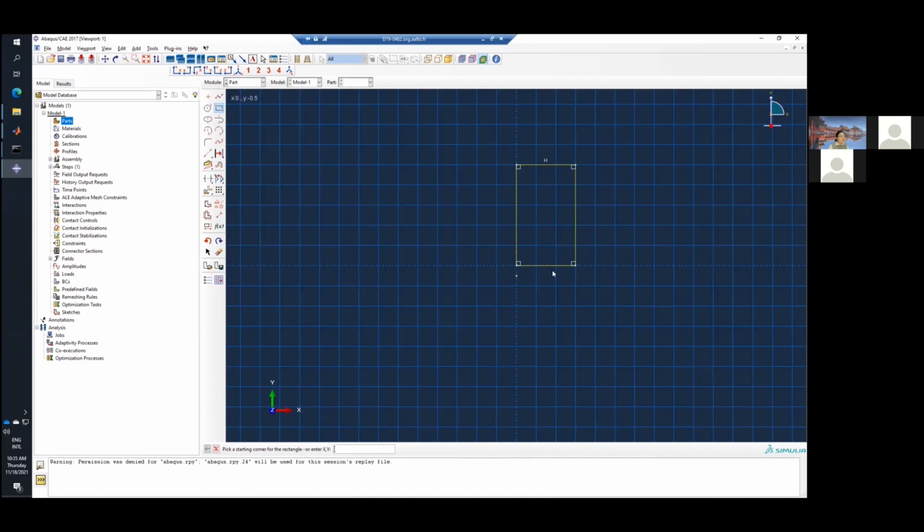And if you want to make sure the dimension or the size of each of your lines, you just click this one, this Add Dimension icon, and choose your lines and move it. Then click it to fix it. So now it's already 3. It's already what we want. If it's not 3, you can change it here.